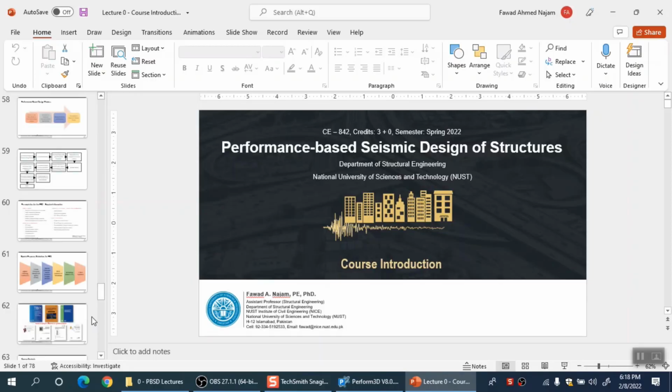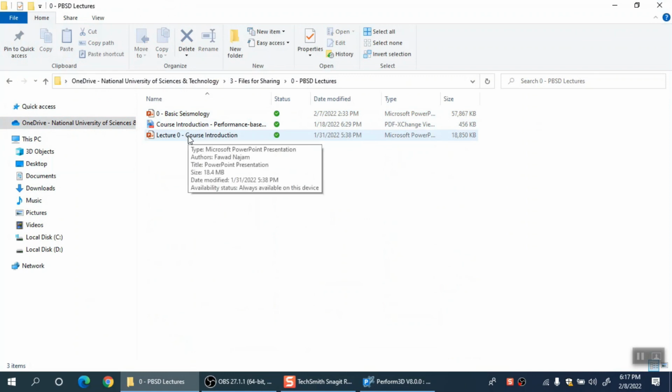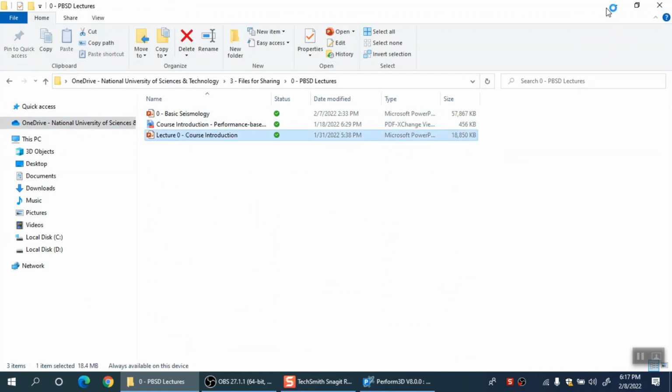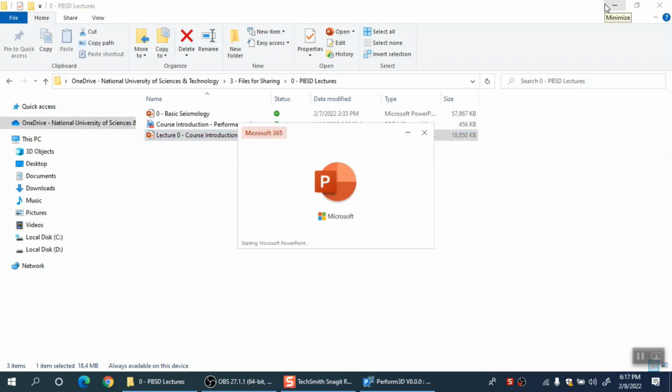In a nonlinear computer model, you can also model nonlinear partition walls. So if there is any cracking in a partition wall, it will be captured in your model, right. One of the limit states or performance levels can be cracking or significant cracking in a partition wall. So in the same pushover curve or during the earthquake, you can see which partition starts cracking at what time actually, right. By the end of this course, you should be able to make a nonlinear model, run nonlinear analysis and produce these kinds of results, right.